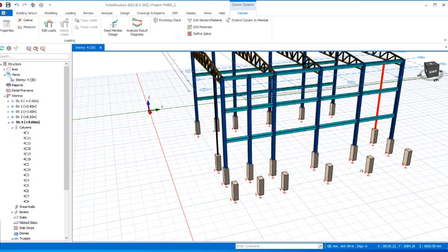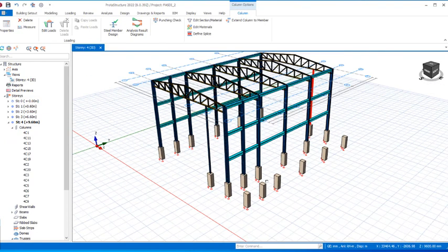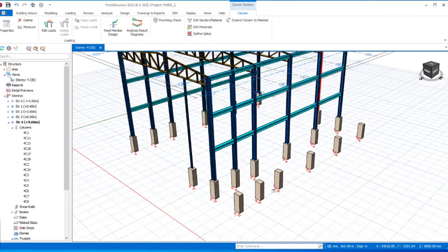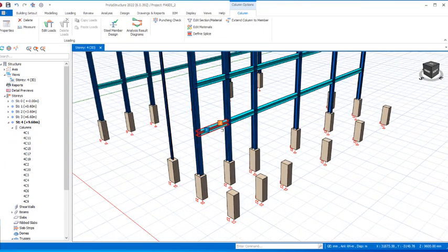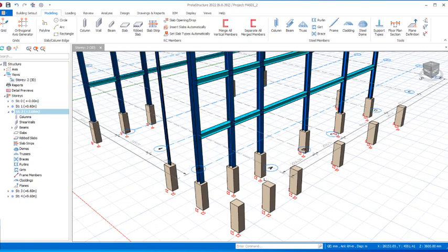After we must have done that successfully, we want to be placing a column on this other reinforced concrete foundation columns. We want to be placing the stanchions, and we will be using these stanchion sections. We have to be at story 1 to place it successfully. So we navigate to story 2.